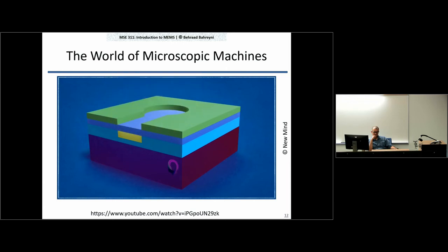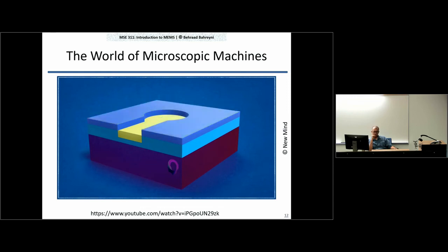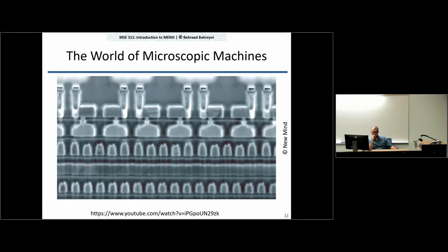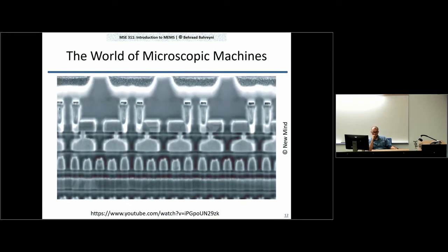The unmasked oxide layer is chemically etched away and the remaining photoresist chemically washed away, and this process is repeated dozens of times using the remaining layers of oxide as a mask for each subsequent layer. The buildup of layers of material with different semiconductive properties form the circuitry of the chip.